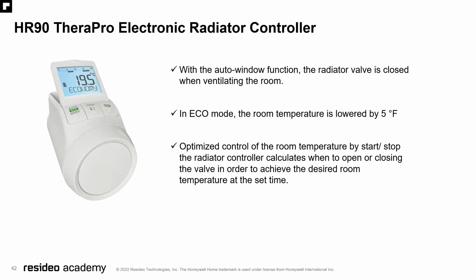It also has a built-in auto window function. The radiator valve closes when venting the room. It basically can sense if there's a radical drop in room temperature, indicating that a window is open, and it will go ahead and shut itself off so that you're not just pumping heat outside. That's a popular function for landlords.